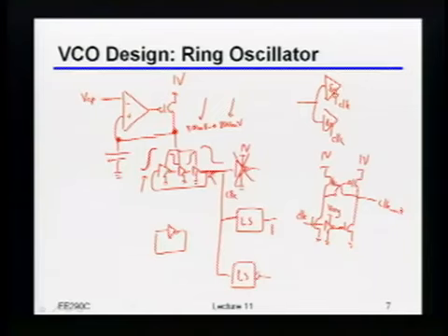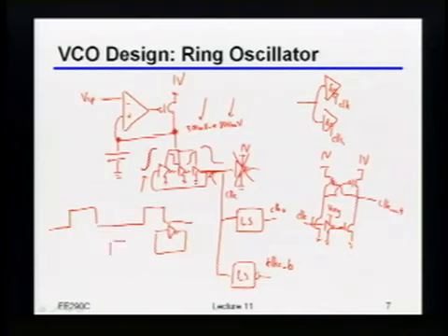So why is the duty cycle not 50% starting? I don't quite get it. Oh, because remember, I didn't do anything to change that. If I looked at the duty cycle of each individual clock, I didn't do anything to fix that, right? So if I draw these waveforms, for example, let's say this is clock O, and this is, let's say, clock O bar. What I'm basically saying is clock O might look something like this. Clock O bar will look something like that.